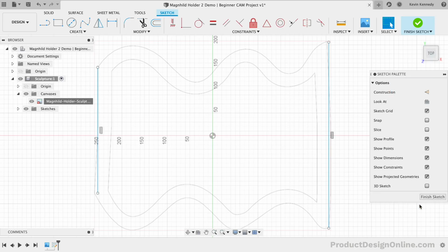To trace this interesting curvature, we can use the Fit Point Spline tool. You'll find it in the toolbar or the Create dropdown. We'll start the spline by selecting the endpoint of our line on the left. Each time we click with the spline tool, we create another spline point. We'll want to click at each peak or vertex of these curves, minimizing the number of points we use.